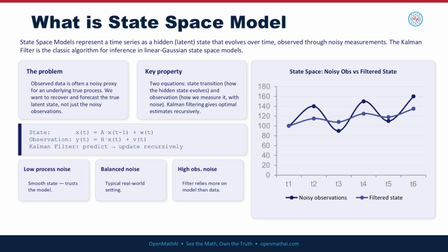A state space model works using two main equations, the state equation and the output equation. The state equation calculates how the internal states change based on the previous states and current input values. The output equation then uses these internal states to calculate the predicted system output.